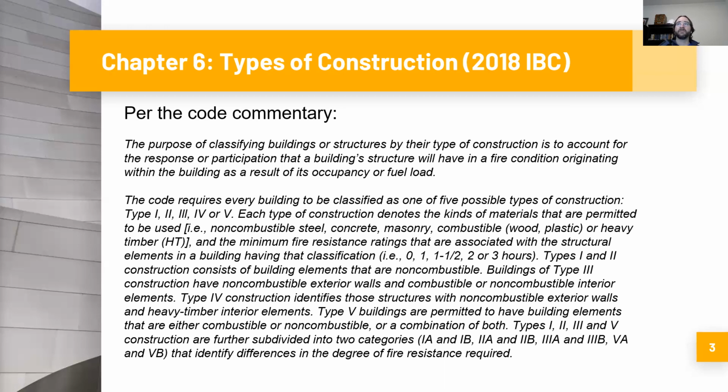So you can have non-combustible fireproofed buildings, you can have non-combustible non-fireproofed buildings, you can have combustible fireproofed buildings and combustible non-fireproofed. And of course, when I say fireproofed, I mean with fire resistance rated materials applied to it, generally referred to as fireproofing. So the point is you have essentially four different types of buildings that you're looking at here.